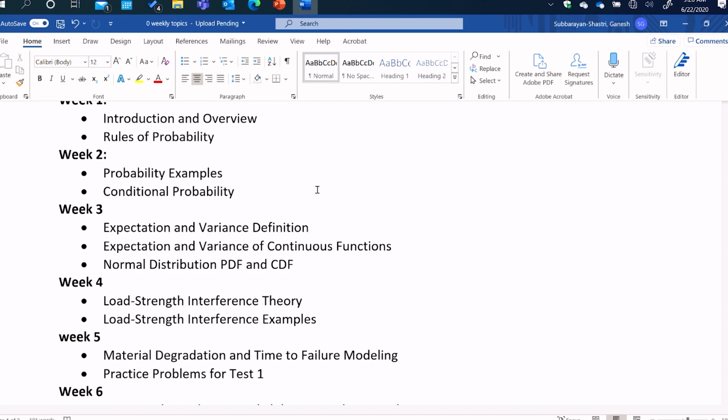Since reliability is concerned with characterizing uncertainty in failure times, and failure times are often complex functions of design parameters, we need to be able to understand what the uncertainty in an output, in a general output function performance metric, will be given uncertainty in the individual design parameters that we try to influence during the design phase.